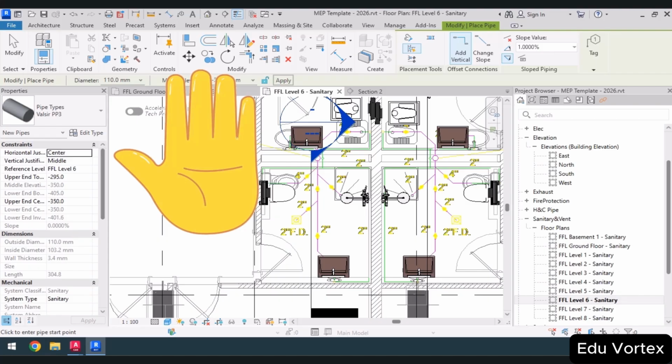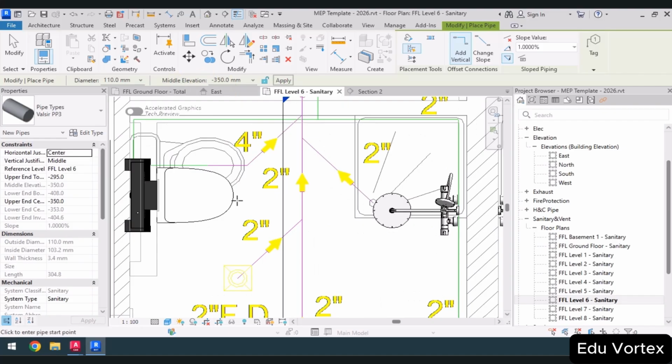drawing. So if you skip this process, mistakes can occur since there are many plumbing items requiring configuration, and you may forget them. So we check these 5 items with our fingers before starting modeling. Near this fixture, I click once and move slightly forward. Our wastewater connection has a 45-degree angle to facilitate a smoother flow within the pipe.